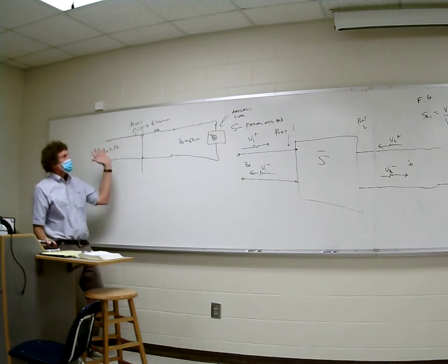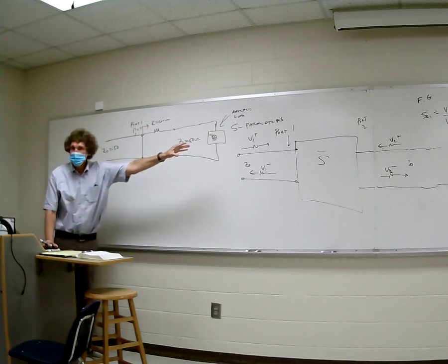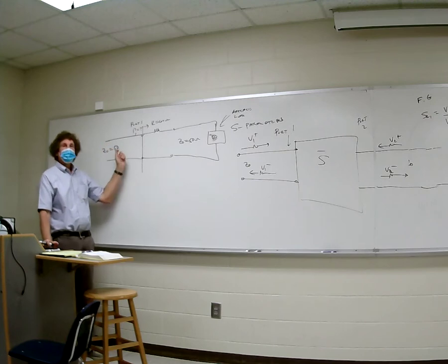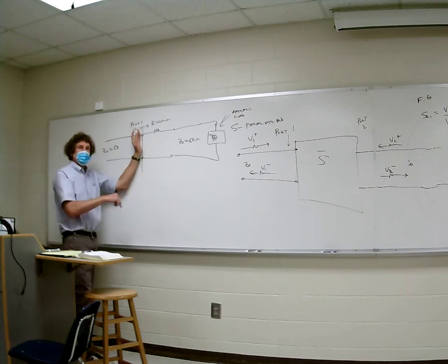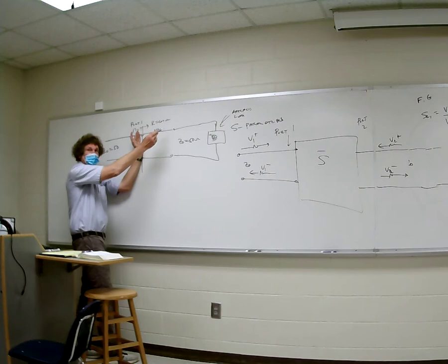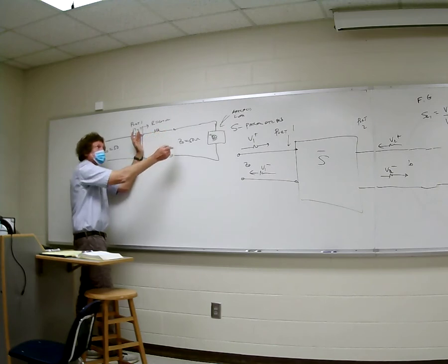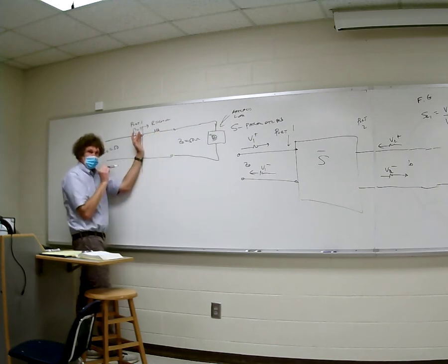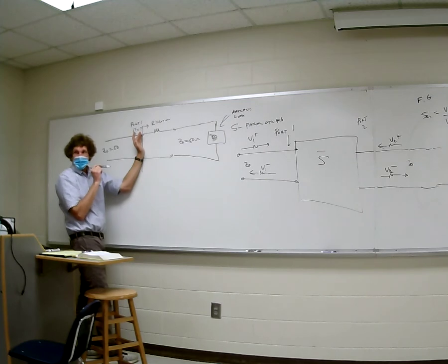You look at the impedance you're going into, right? And you subtract it from the impedance you came from, and then you divide by the sum. Y'all remember that? So what's the impedance you're going into? I gotta make sure you see this. Well, I got 100 ohms here for sure, right? And then I got an additional 50. Now that's matched, all right? So it's just 50 ohms. You all see this? So I'm going into 150 ohms.